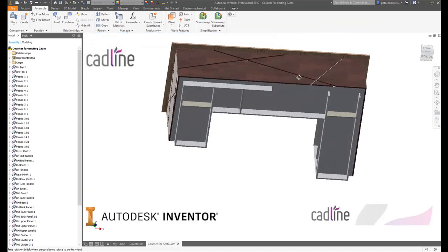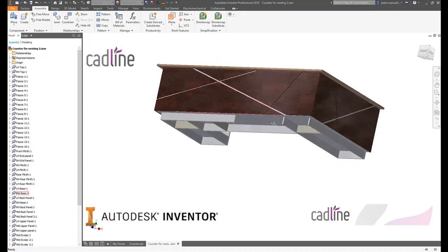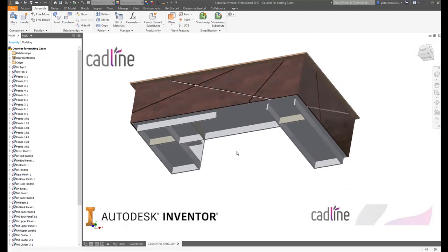and you see I have now created an assembly, but I've got a couple of bits missing, and these ones I want to be duplicates of it. Now I'm not going to use my mirror, because I'll end up with this part as being front plinth, and then the mirrored side would be front plinth MIR, and there'll be two separate parts. So instead I'm going to use a pattern. However, I don't know how long to pattern that, and because it's parametric, that pattern length might change. Okay, so I don't want to just go here and measure that and then put 1175.